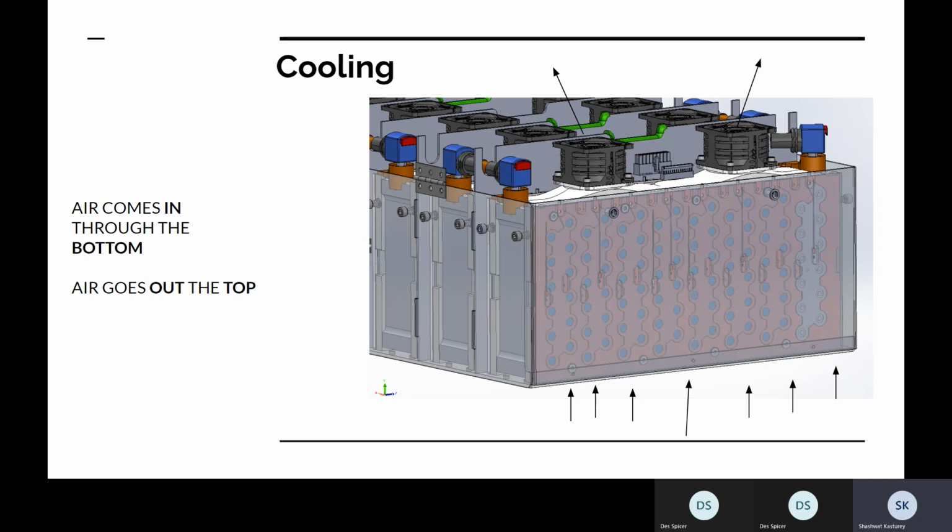You said earlier that sometimes the air close to the ground is super hot. So would it be worth thinking about pulling air from higher off the ground? Yeah, absolutely. We talked about some kind of louvering or ducting made of carbon fiber that would pull air in, basically as a ram air intake from the side of the car or the top. But we were so committed to this construction of the battery pack that it would be completely infeasible.